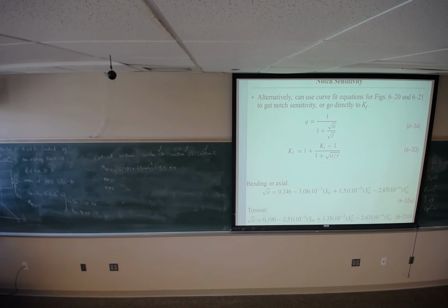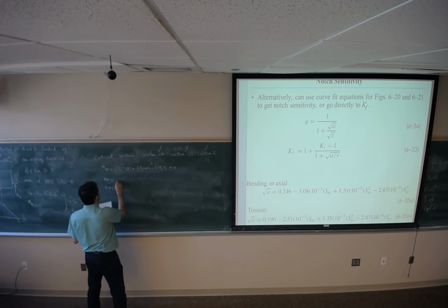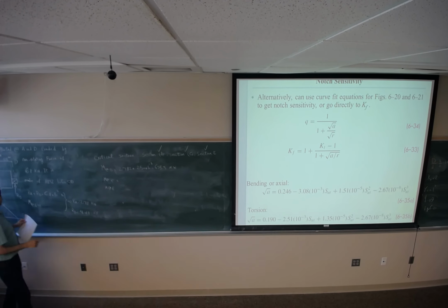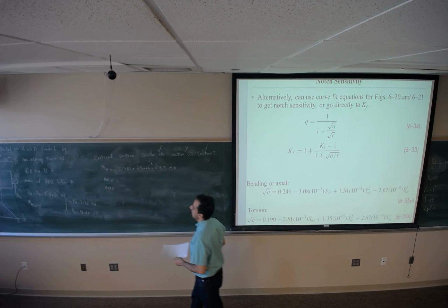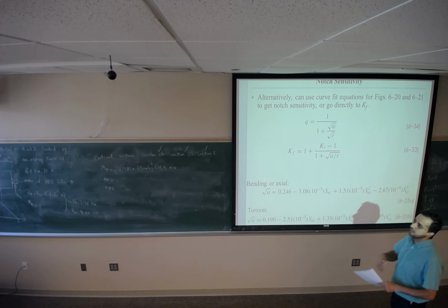At point C, how can I find the bending moment? Either by multiplying this force by this distance, or multiplying this force times this distance minus this force times this distance. Either way, we will get the same result. We have covered this in the beams.